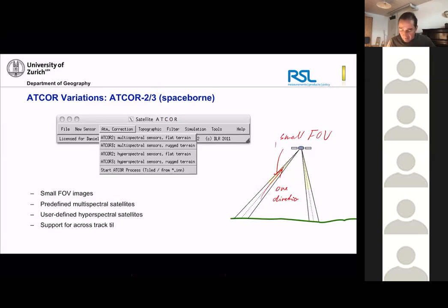That's the satellite situation for standard high resolution imagery. You don't have a lot of variation of observation angle within the image. Nowadays that's no longer very true. So for large Sentinel imagery and Landsat imagery, we have to take the direction within the image also into account. But for most standard high resolution satellites, this is a good approach. Then you only take the average direction into account.